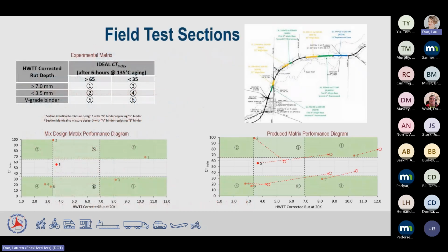So the first one I want to show you is those test sections on State Highway 69, just south of Madison. You can see the plan and where all the test sections are located up in the upper right corner there. It's kind of hard to see, but using the FWD we tried to find where an equivalent foundation was along the project, because they had all different materials under there. There was concrete, virgin base, combinations of both. So we took the FWD out there and tried to find an equivalent foundation to build the surface layers on.